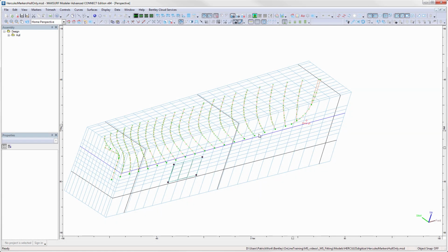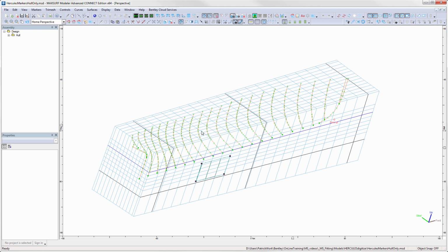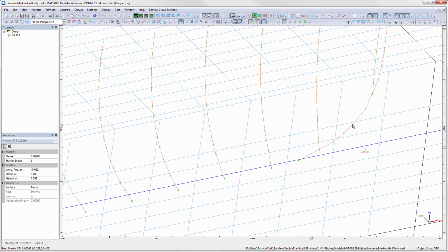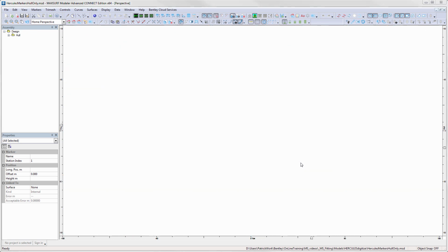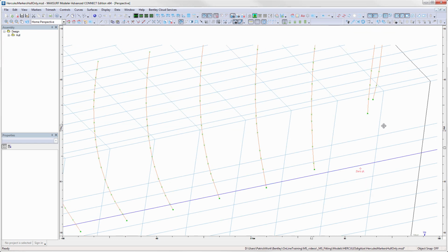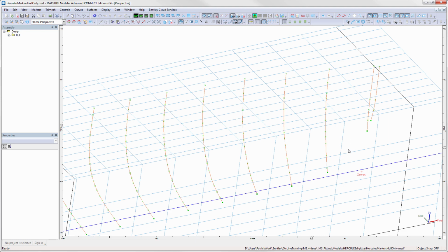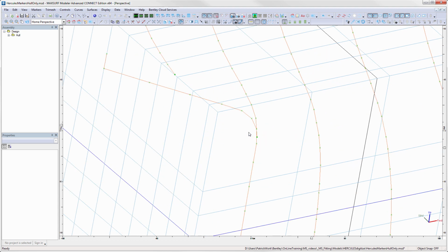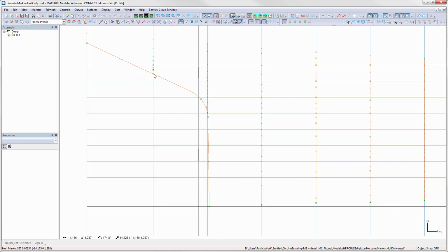Now I'm going to load in the markers that I generated by digitizing the lines plan. So what I need to do if I want to define a tri-mesh though is to make sure none of the sections actually overlap. So here where I've defined the stem profile, I've got some overlapping points here which I need to get rid of. So I can do that just by selecting them. If I use the shift button, I can add to the selection and then just press the delete button. So now that stem profile doesn't overlap the other sections. In fact, the sections don't need to be planar, it's just the overlapping that's the problem. In fact, what I should do is leave that one because that forms part of that station, but I'll get rid of these.